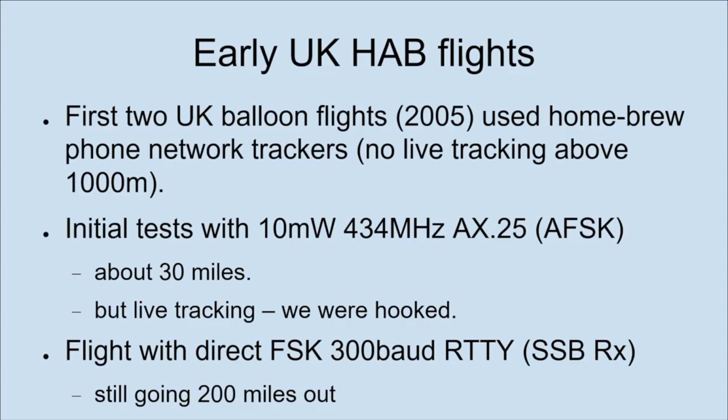So we did some initial tests with 10 milliwatts on 434 megahertz using the same standards as APRS, and got about 30 miles doing that. It certainly proved that the tracking capability was there, and we were really impressed by being able to track through the entire flight. But it just didn't have the range to give us confidence, particularly at that time, about being able to keep in touch with the balloon throughout the flight.